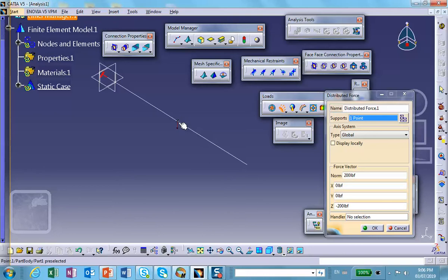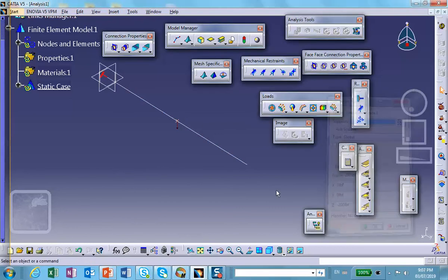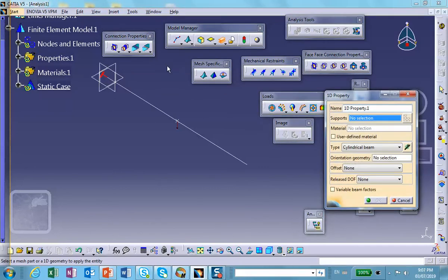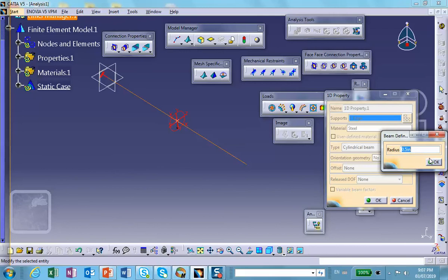In other words, repeat this thing, but do not go to advanced meshing tool to include that point. Just try to do exactly what I did. You'll see that this load that you put here will not affect the beam deflection at all. Now, the only thing that I have to do is the cross section of the beam, which is this. It's exactly the same thing that we had before. Width 0.5, and we're gonna run it.